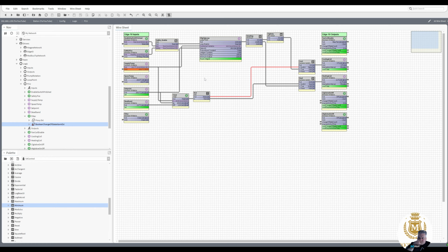We've still got to do the fan enable because at the moment the fan's not on. So we can follow that through with the loop enable if we want to, or we can just take it from there. Let's just take it from there. So that's our fan started. So we've sorted out them two valves. We've sorted out the fan coil enable. We've got to do something with these in case they don't use 0 to 10.